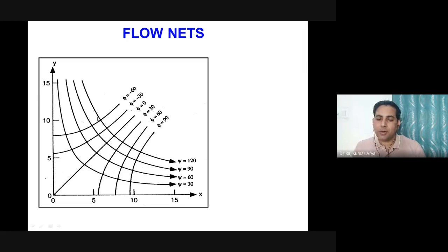The only thing is that at the point where they intersect, they are perpendicular at that particular point, no matter what is happening in between, because from here to here you don't know. But practically, if you want to draw all the streamlines, all the stream functions, you will have seven streamlines in between. So every point where they intersect is actually a 90-degree angle. Okay?